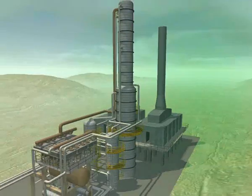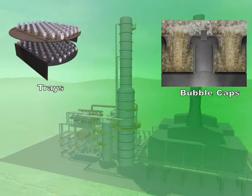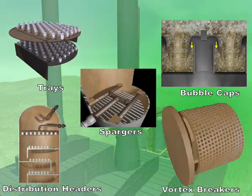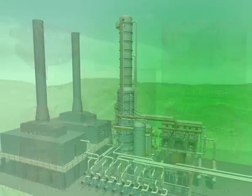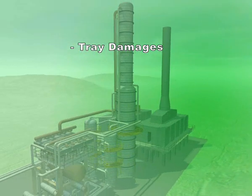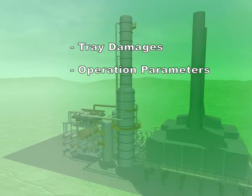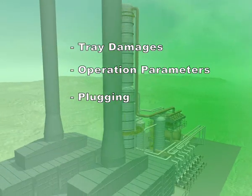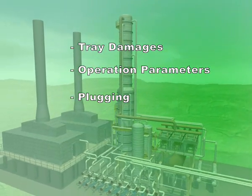We looked at various internals like the trays, bubble caps, spargers, distribution headers, and vortex breakers. Other subjects covered include causes of tray damages and the results thereof, the effect of changing the operation parameters like reboiler temperature and draw rate, causes of plugged trays and distribution headers and their symptoms.